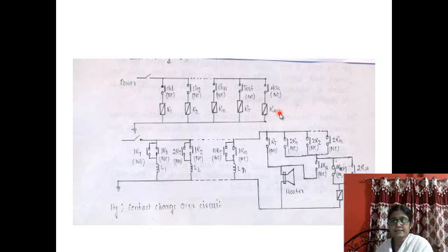But after releasing this acknowledgement switch, this will again move to de-energized state, and as this moves to de-energized state, this circuit will again break. So RH will again move to off state, and if it moves to de-energized state, again this circuit will make the hooter circuit. So again the audio signal will be produced. That is hazardous, so that should not be done.